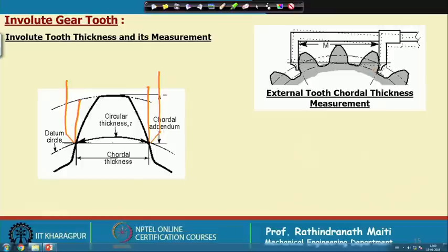In this case it is shown, this is 3 teeth, okay, and it might be more depending on the gear size. Minimum 3 teeth is required, and then if the gear size increases, then the number of teeth also increases. But interestingly, if we consider this from this point to this point, this must be base pitch. Similarly, from this point to this point, base pitch.